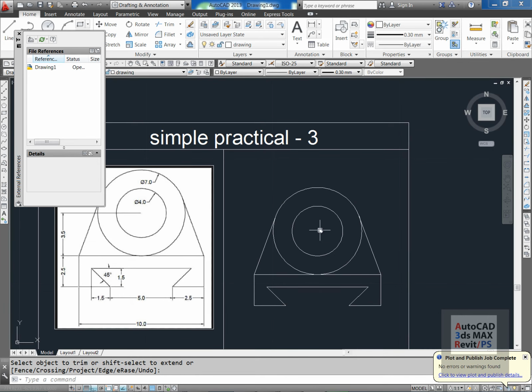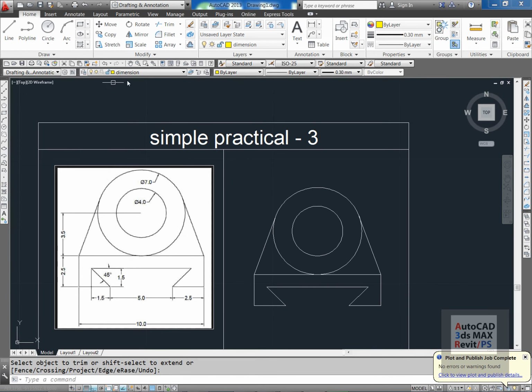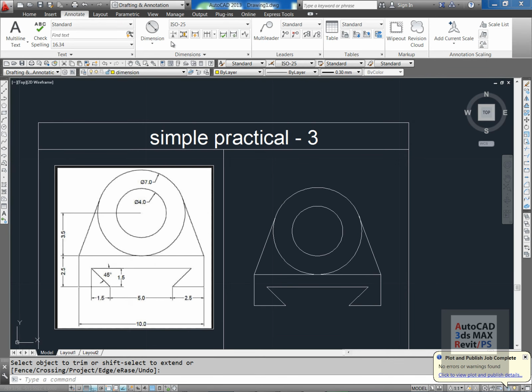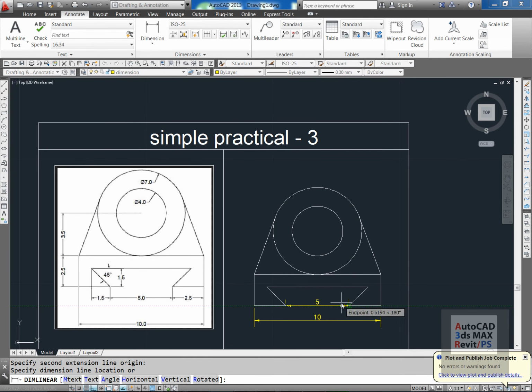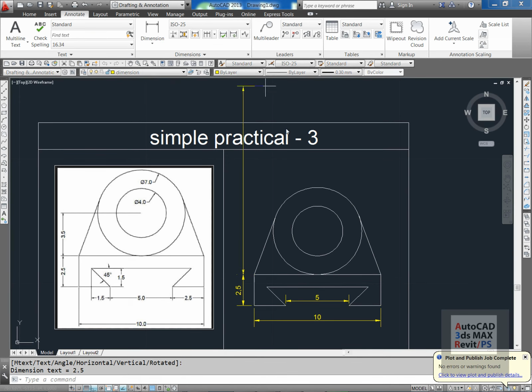The only part left is dimensioning the drawing. So let us take the dimension tool. I will go to the dimension layer and start giving the dimensions. The first dimension is linear. I will go to the annotation panel, choose linear, selection 1, selection 2, and again selection 1, selection 2. Then you can choose continue and mark this point. Also, you can mark this point to look better.